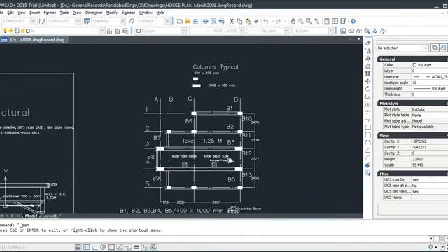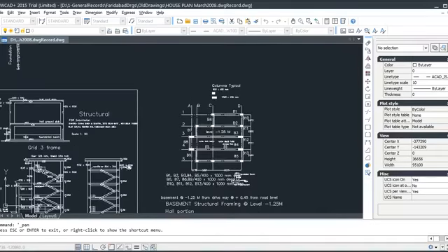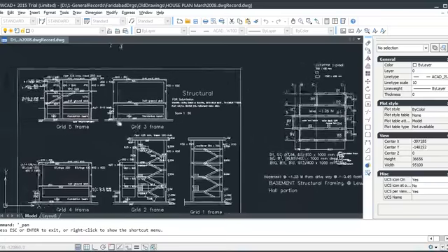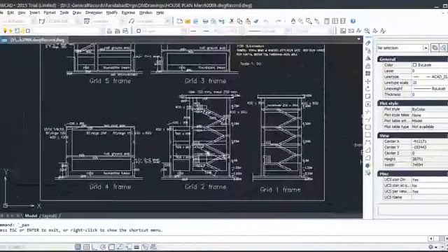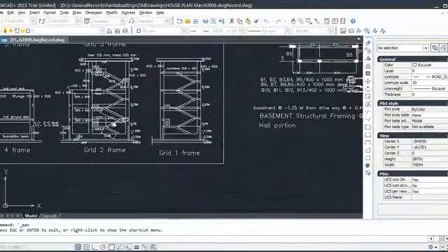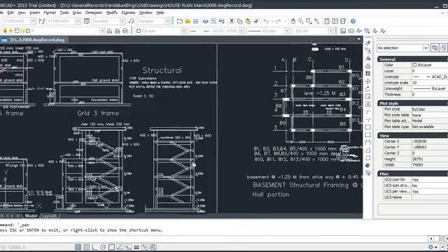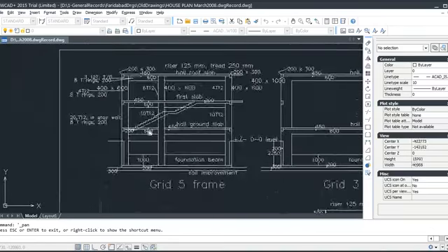Certainly there will be some out of line action. That was considered, and I took conservatively a seismic moment, you can say 25% of vertical load, and then applied them accordingly. So there are so many considerations in buildings. You can say everywhere it's like that.